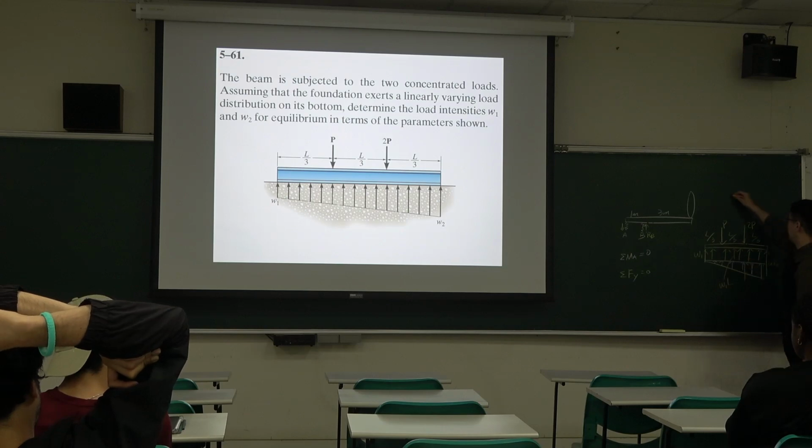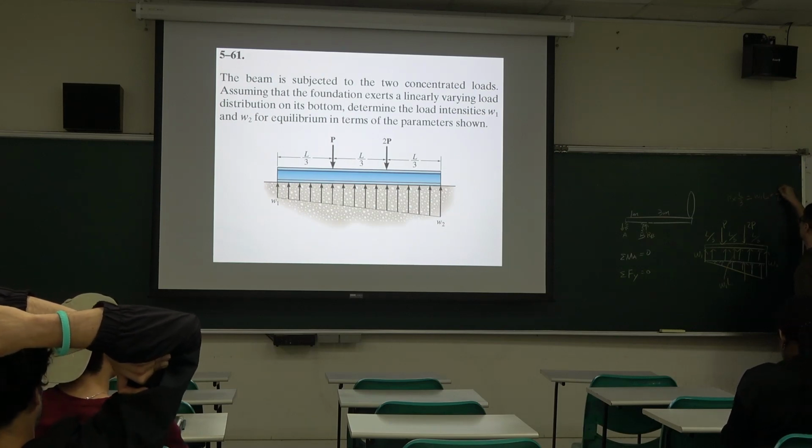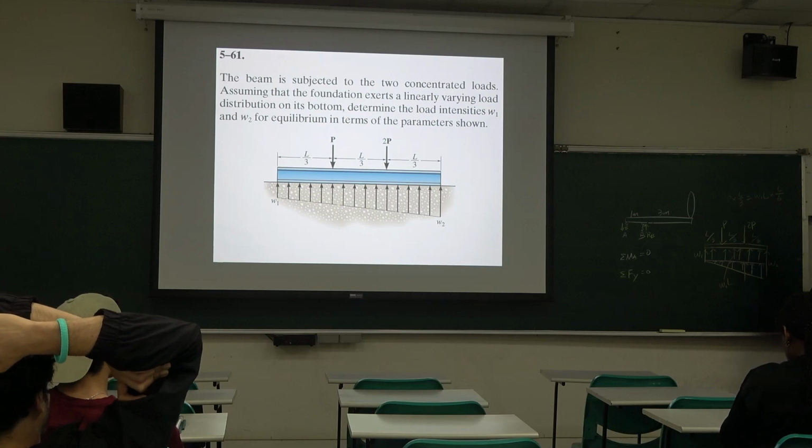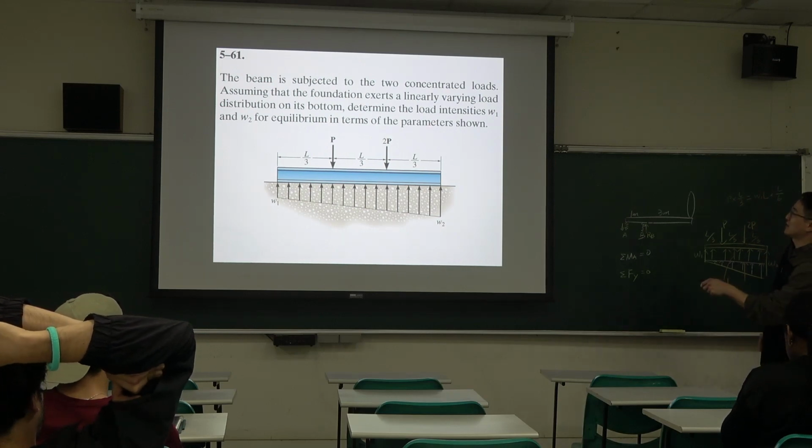So that means P times 1/3 L should be the same as W1 L times 1/6 L. So you can work out what we need to determine.